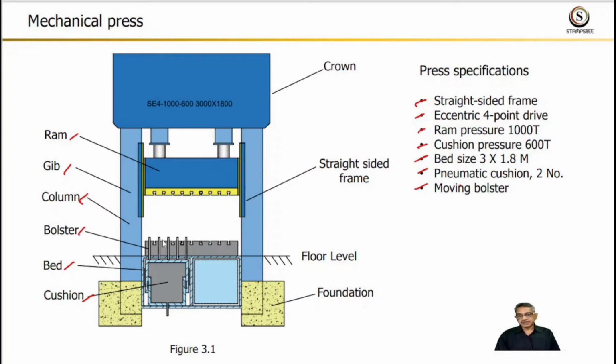To verify the current state of the press parameters, a few tests are carried out such as bolster flatness test, ram parallelism test, jib clearance test, cushion parallelism test, ram motion squareness test and main bearing clearance test. Now we are going to discuss all these tests in detail.